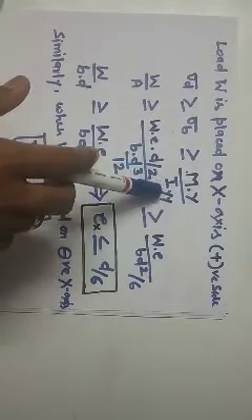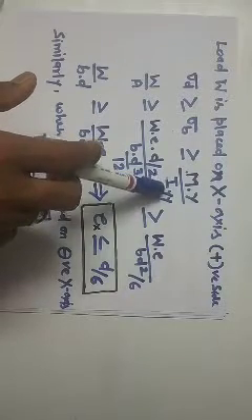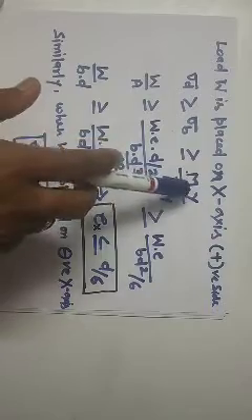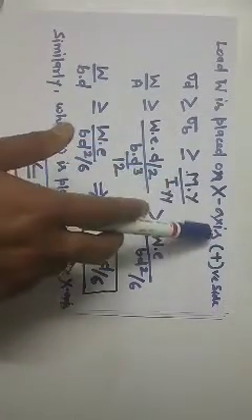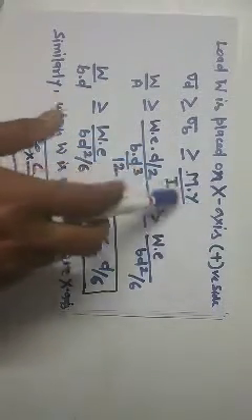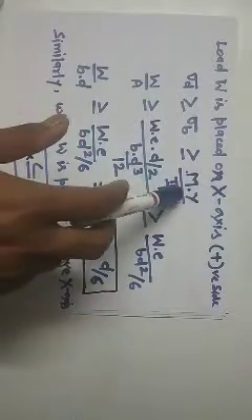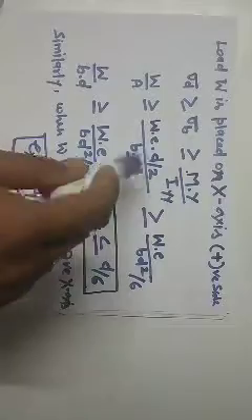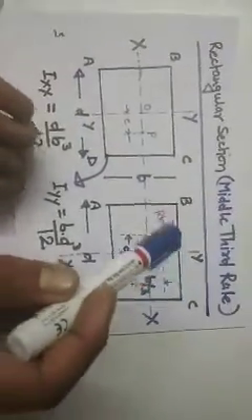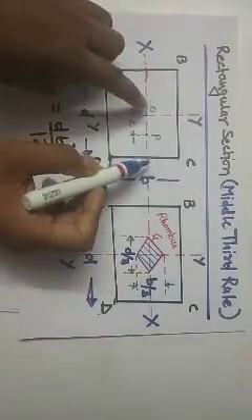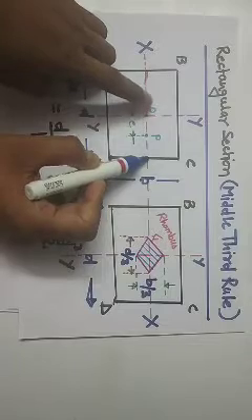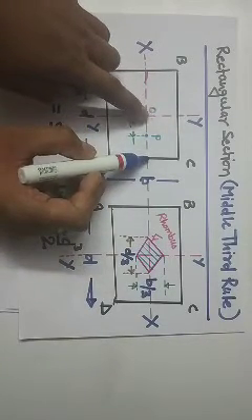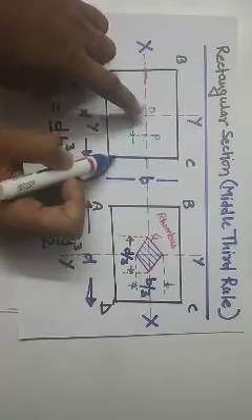And this is I_YY. What I said earlier is that when load is placed on an axis, then we will take M_Y about the y-axis. This is I_YY. Now y will be equal to d by 2. This is our y, the top fiber, and the distance of the top fiber from the centroid will be d by 2.